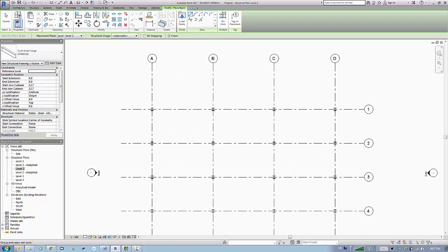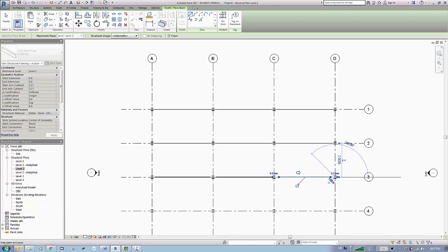And take your time to connect them one by one, one at a time. Escape and continue here. Don't just stretch them in one line. That one will be good structurally, because it will be different. It will be a continuous beam, which we don't intend to have any continuous beam. These are one beam at a time on 2 columns.